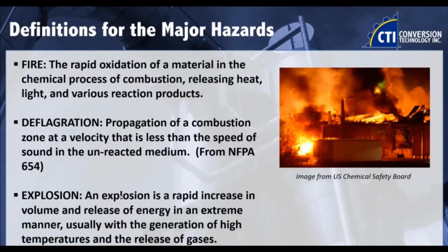But an explosion, I think we all know. The key for a deflagration is that it is what a lot of the standards are written based on. You'll hear fire, fireball, flame front, deflagration. So a deflagration is the occurrence of four specific things. First, small combustible particles are present.